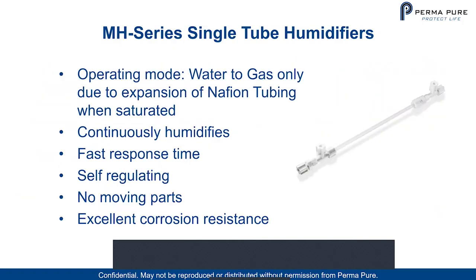So again, the operating mode is water to gas only due to the expansion of the Nafion tubing when saturated. It continuously humidifies. It has a fast response time. It's self-regulating, has no moving parts, and has excellent corrosion resistance.